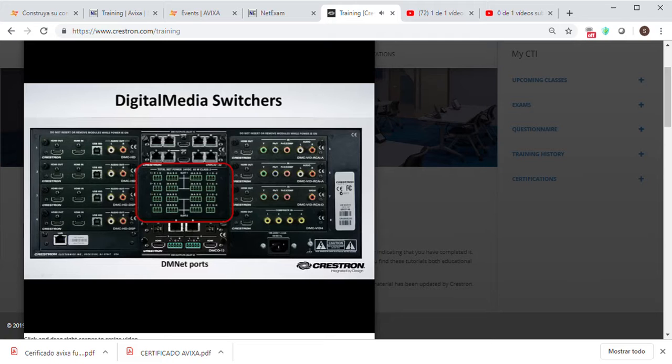For these and other power requirements needed, we have provided an EIG connection port for each DMNet port. Each EIG port connects to an external power supply or to the internal power source via a jumper to power the DM device connected to the corresponding DMNet port. Located on the lower right of the digital media chassis is the power connection for the chassis itself, and on the lower left you will find a LAN connection for connecting to a control system.